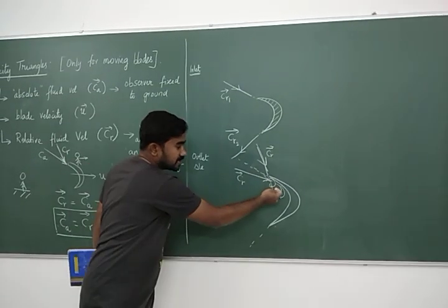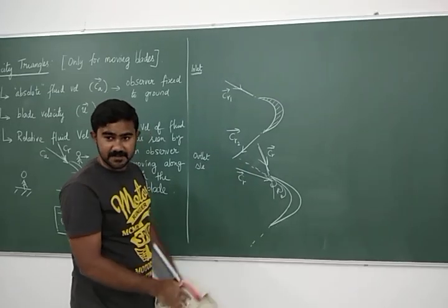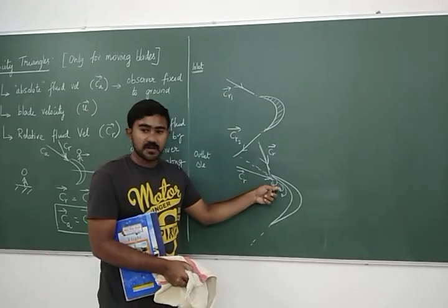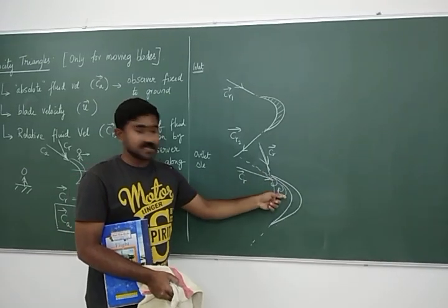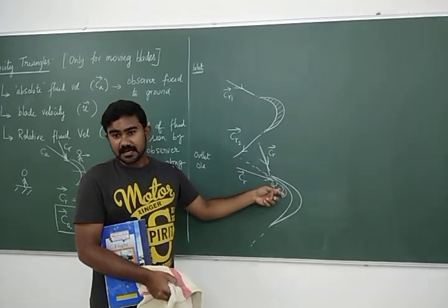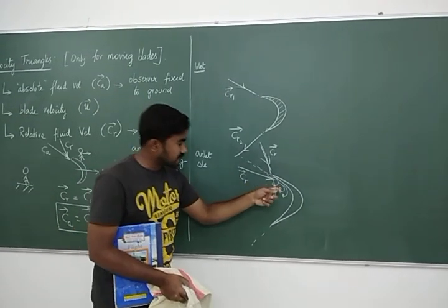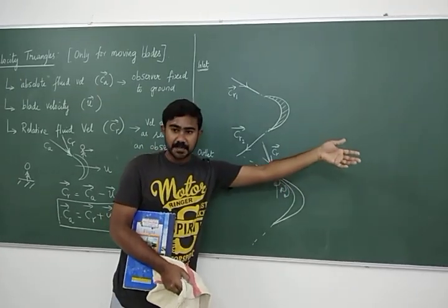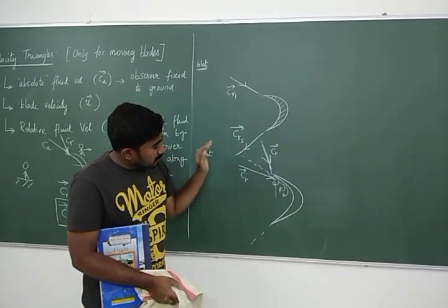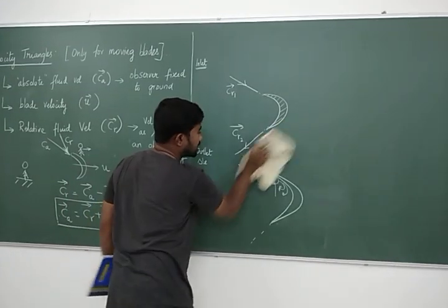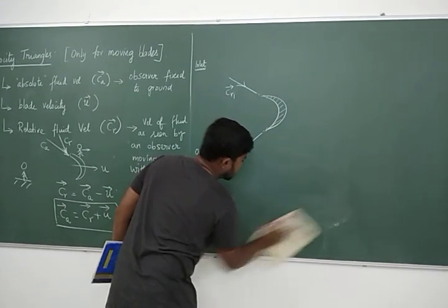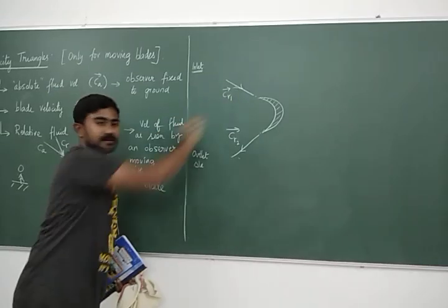So this separation will include a lot of other effects, okay? Because this itself will cause vibration of the blade, and the blade is already moving, it may lead to catastrophe, okay? The blade can even damage because of this effect. It will start from one blade and it will start progressing to other blades also. So to avoid all these complications and shocks, what we do is we have to ensure that the relative velocity vector is nicely aligned to the blade direction.